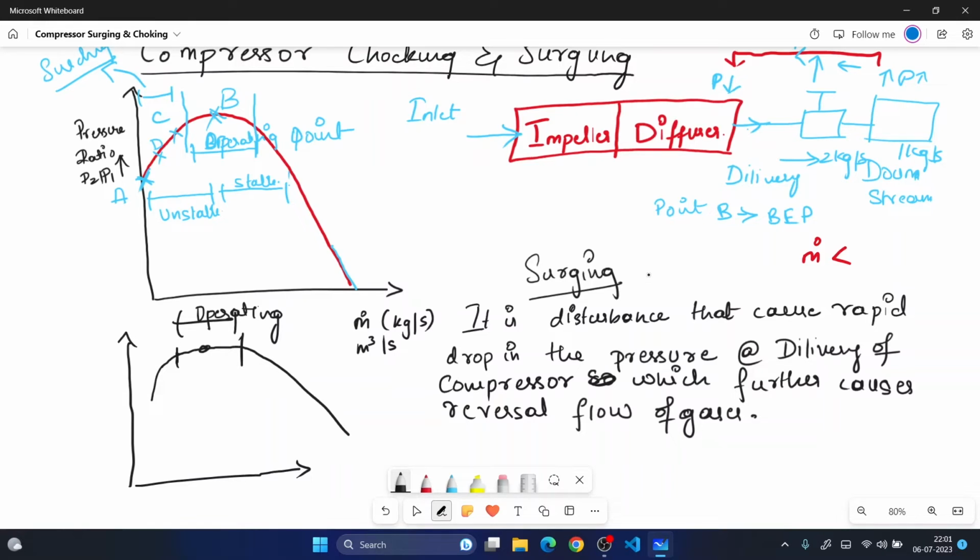Okay, as it can lead to a catastrophic failure of the compressor, which may increase the downtime to repair, and it may also increase the operating cost. It may significantly affect the bearing life. So what usually all the manufacturers do is, when they design or manufacture a compressor, they usually have a set point, a safety point, and if surging occurs beyond that point, the compressor shuts down immediately.